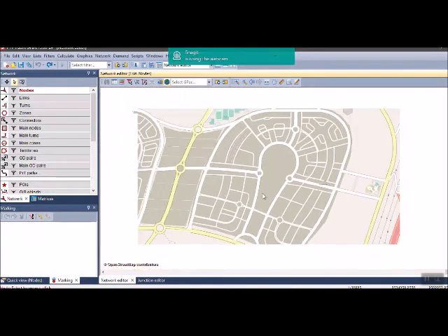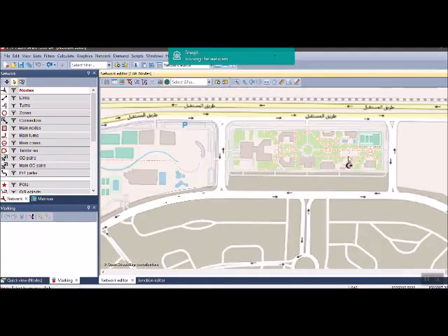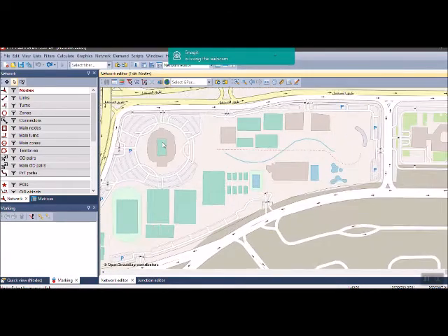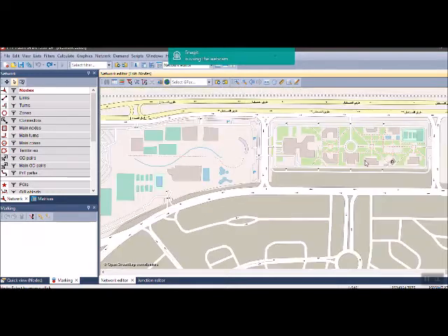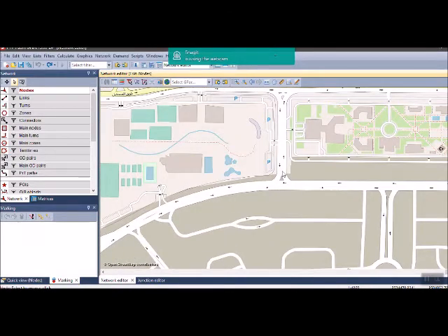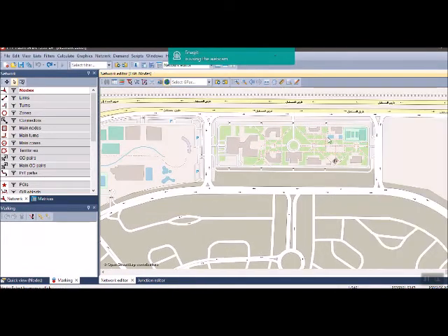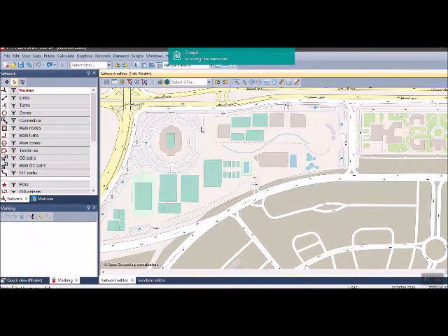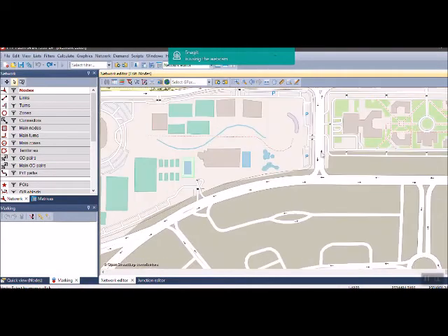Another thing: if you have a residential zone like this and another residential zone, or this is, I think, a stadium here and there are some parks here, so they are recreational zones, zones which people go to for recreational trips on their weekends. But I have a major road between them. So even if I have a homogeneous zone here and this zone is homogeneous in its characteristics like this one, it is better to divide them because there is a road between them.